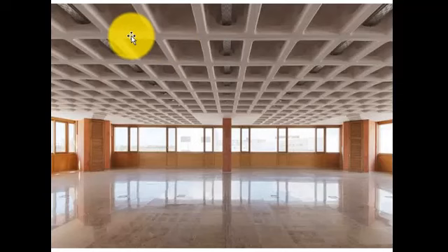So it is 2-way. But if you see the rib slab, you can see that the rib is only in one dimension. It is 1-way. Look at it. There is no other rib crossing it. You understand? Therefore, it is a 1-way waffle slab, or you just call it rib slab. Any which one you like.